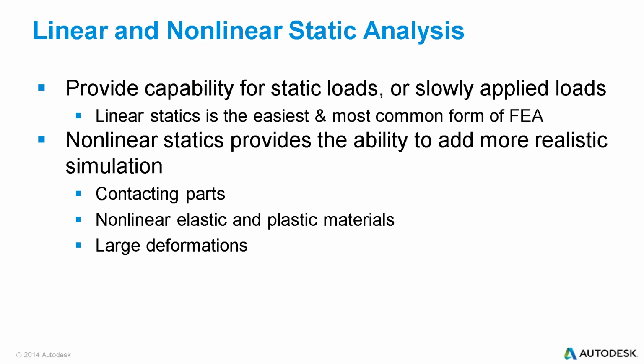For a nonlinear analysis, you get more detail of what's going on. A lot of different things you can get from the results. You can see how contact between parts actually pushes stresses into other components and how the material itself might behave under certain conditions.